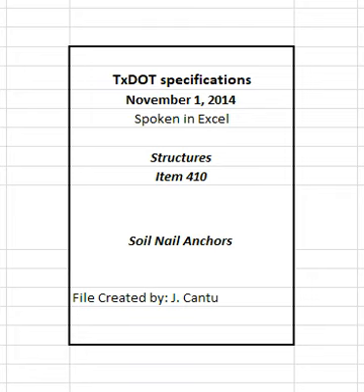Grout each nail within 8 hours of the completion of drilling. Holes open longer than 8 hours will be rejected and backfilled with grout. Grouting before insertion of the epoxy-coated bar into the hole is only allowed with approval. If approved, advance the grout pipe to the bottom of the hole and leave it there until the hole is filled with grout and enough unsegregated grout is expelled at the top of the hole. Withdraw the pipe slowly while grouting continues, filling the void left by the grout pipe.